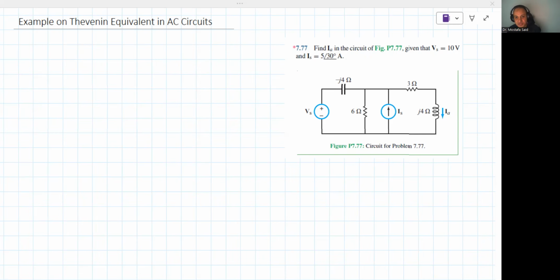So what Thevenin says is that you can take any two nodes in a circuit. For example, you have a resistance. This resistance has two nodes. Just look from the perspective of that resistance into the circuit. The resistance will see two things: a source and some reactance, if it's an AC circuit with inductors and capacitors.